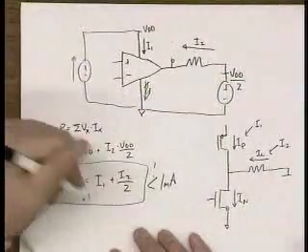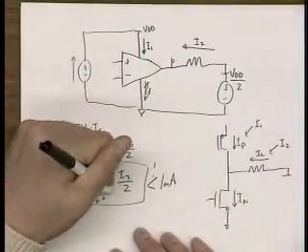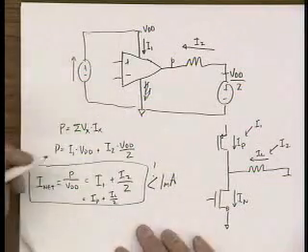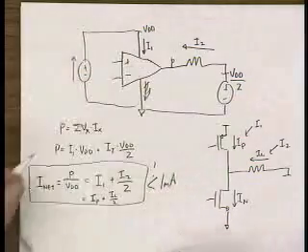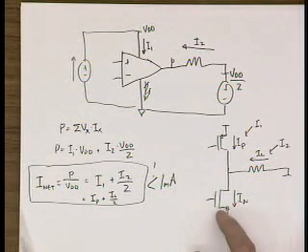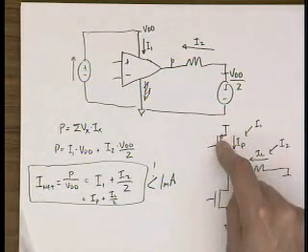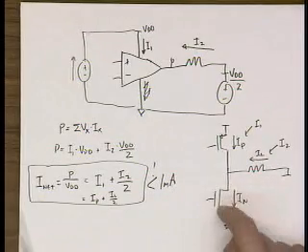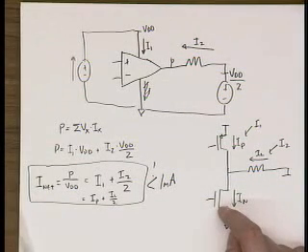So this is equal to IP plus IL over 2. Okay? I intentionally didn't draw what's driving these gates, because I don't know how you chose to implement this. I don't know if you chose to implement this as a common source NMOS with a PMOS current source load, a common source PMOS with an NMOS current source load, whether or not you did something funky like a totem pole driver, and that's something that we were talking about in office hours today that I'll touch on briefly.